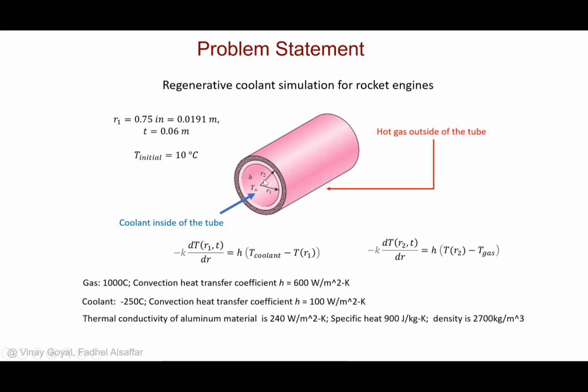So one way is as a shell element, assuming that the axial thickness, that depth value, does not matter, and we want to see the temperature variation in this direction. Then we'll do it using another way, using an axisymmetric element, and we'll see that using these 2 ways, we can get the same results. So let's start now.